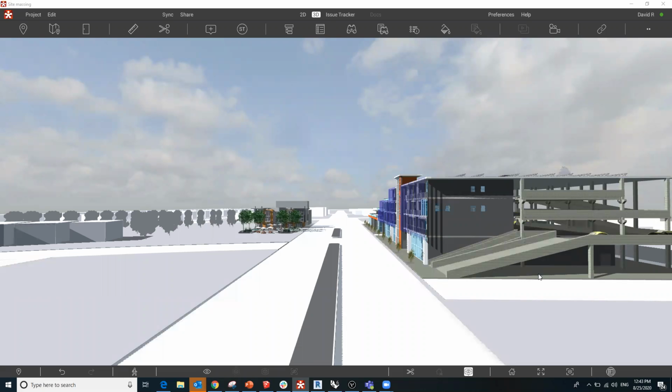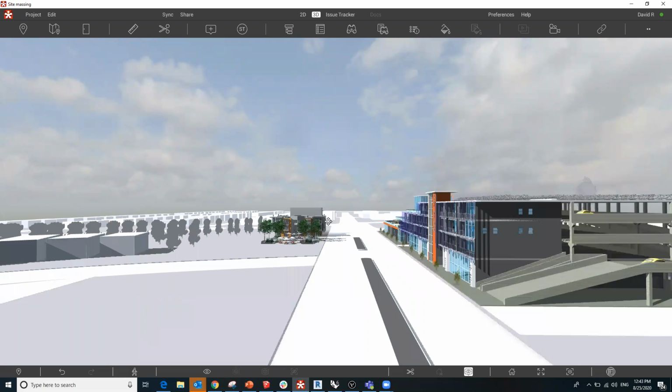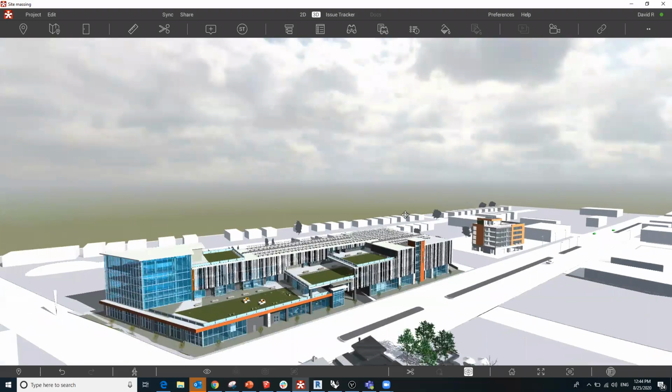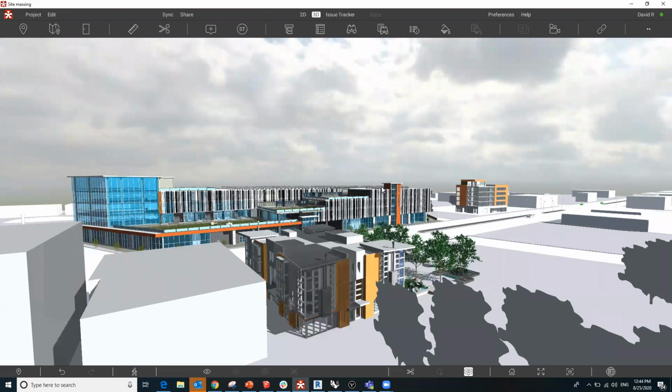And a bonus in 5.0 when dealing with Civil 3D is that, since we now have various search sets and visibility options in Revizto 5, instead of cleaning up that Civil 3D model in Navisworks, you can do that visual cleanup inside of Revizto, really streamlining that workflow with the civil data. Great question, Mark.